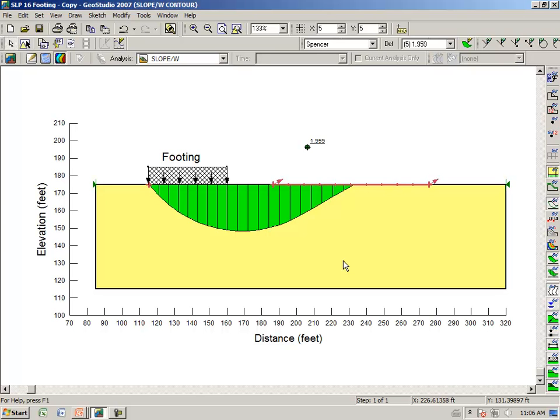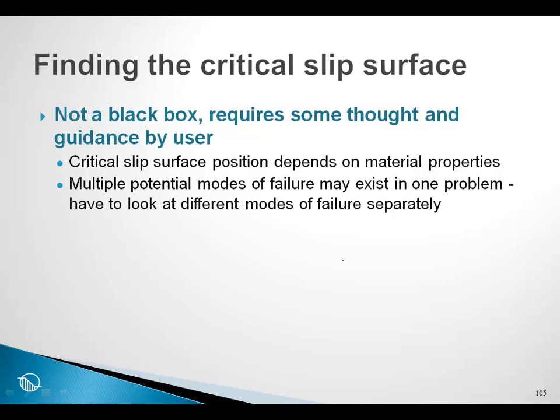In summary, we can control by a specified projection angle the passive end of the slip surface and the active end of the trial slip surface. This then brings us to the end of the session on defining trial slip surfaces.